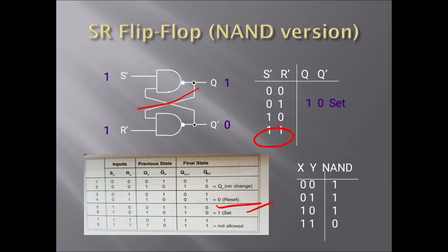this one is treated as input to the second NAND gate and this Q complement is treated as input to the first NAND gate. We get the values 1 1, that is here S value is 1 and the input is 0. So 1 0 gives output 1. So we get the next